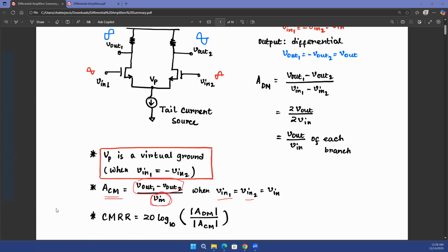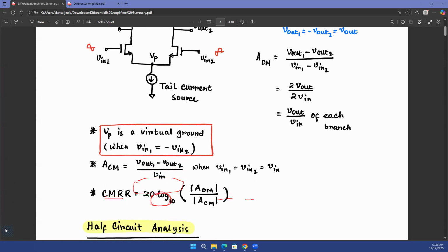Ideally, the differential amplifier should have a very high differential mode gain. Again, if you think about an op amp, an ideal op amp has infinite gain for the difference of the two inputs. Even for an ideal op amp, we said that the output is equal to V1 minus V2 times A. At the output of the op amp, you expect A times V1 minus V2. That is very similar to what you saw for the differential amplifier. So you already get a sense that inside my op amp, there is somewhere a differential amplifier.